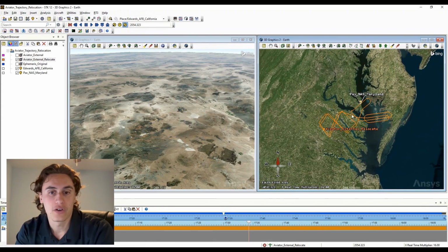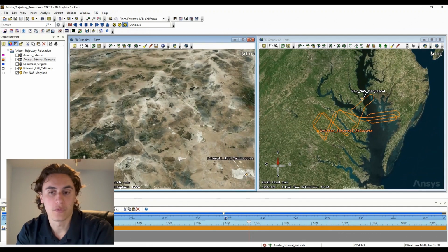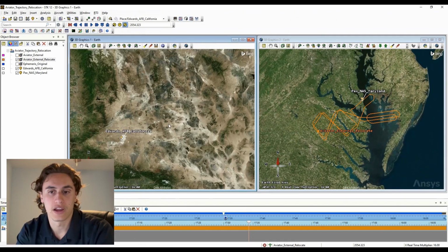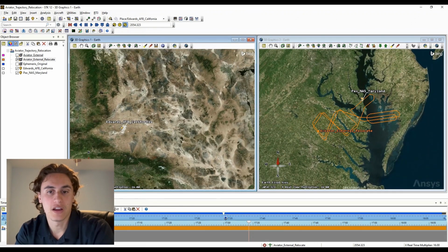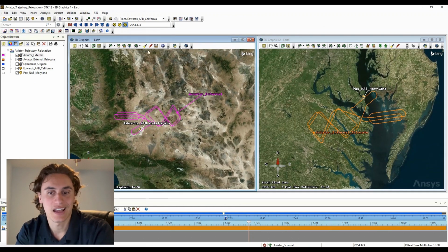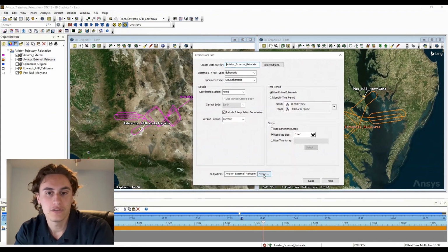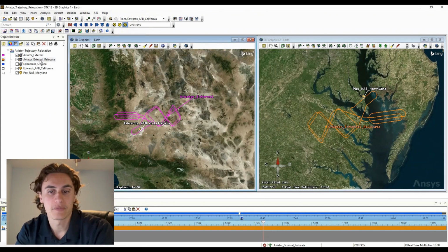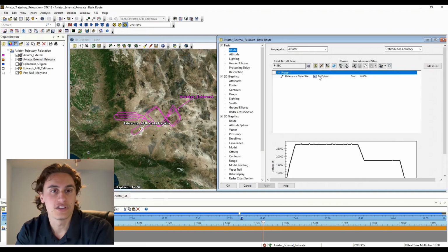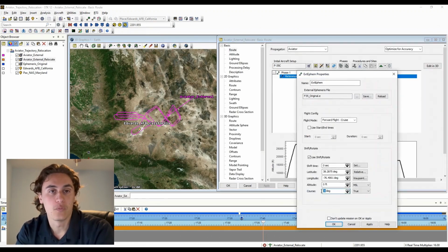And here we can now reevaluate that route at a new range, again with new telemetry and ground stations or new terrain. So this feature can be used to easily shift existing STK objects you've created in Aviator, or also with the Great Arc propagator. So if you were to simply right-click a route that you've created and select export ephemeris attitude from the drop-down menu, you can export an ephemeris file that you can then use with this new added capability. And once moved, you can always easily go back to your initial inputs and make adjustments.